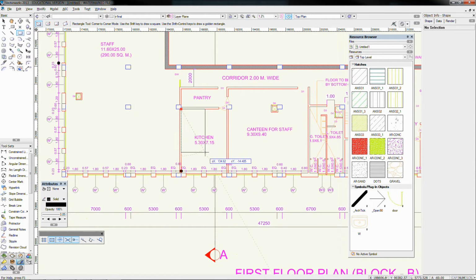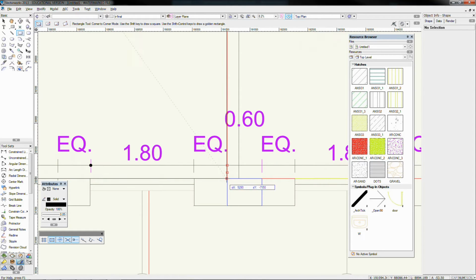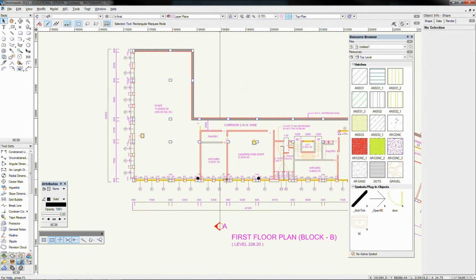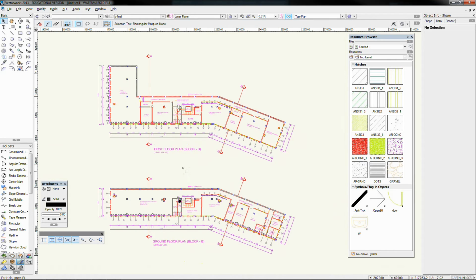And if I just measure the internal sizing of this, hopefully I should get somewhere pretty close on the marker. 5,299 by 6,931. Probably give or take a little bit. There we go, there's that little bit that I'm missing, just down here to this marker line, 7,150. So I would then lock that off and say that's probably the right scaling. I'm not sure what scale that was that we just scaled up by, but I'm going to now knock that drawing off and say that's the right dimensions.